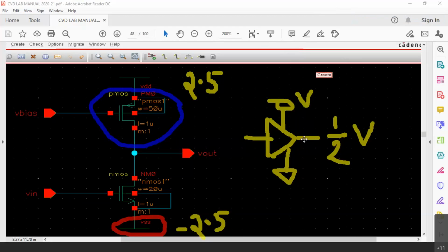So if you use a single supply, let us say you are using an integrated circuit for an amplifier, because the op-amp is an integrated circuit. When you use the op-amp with the single supply, you will have to bias the op-amp so that its output will be half of the supply voltage. Now, this is one requirement.